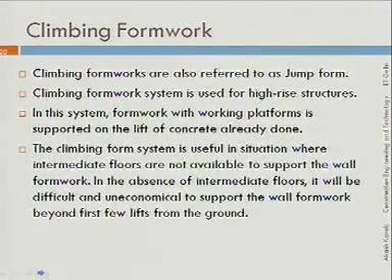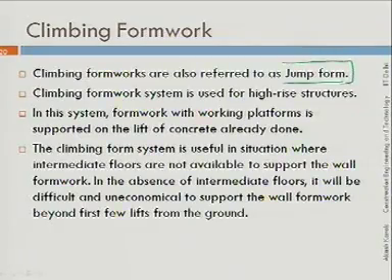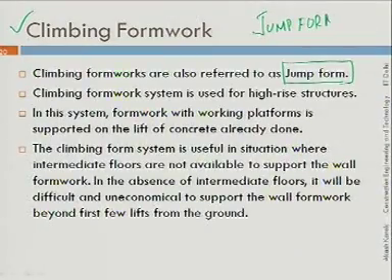Now, we move on to the climbing formwork. Climbing formwork is also known as jump form. In some formwork literature you may come across this name also, jump form. So, both are the same. Obviously, they are used for high rise structures, multi-storied buildings, where the height of the wall is very large. So, we prefer going in for climbing formwork.